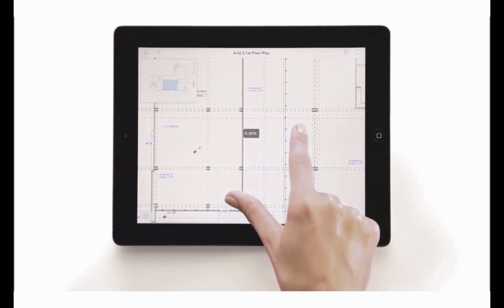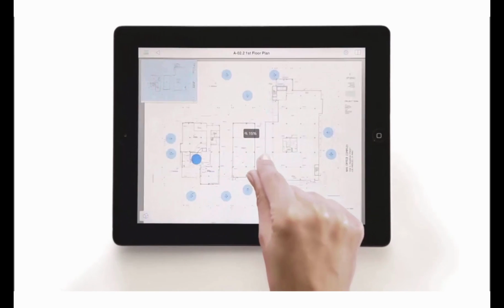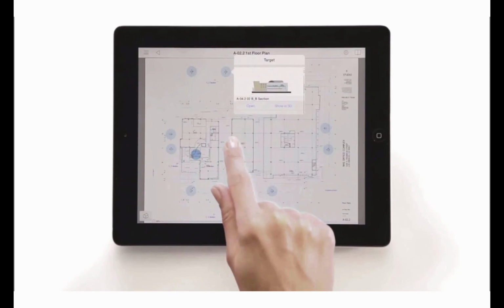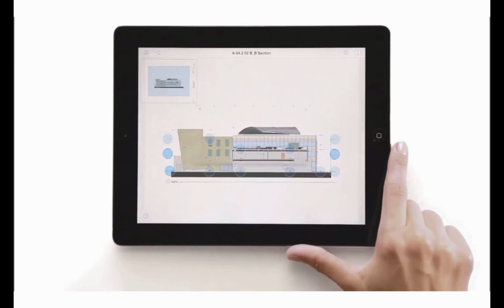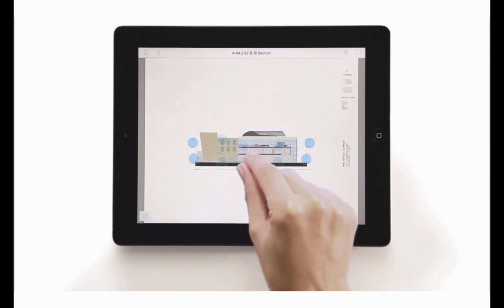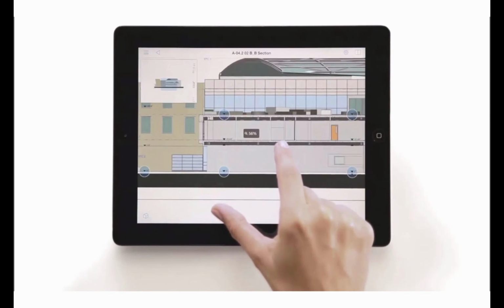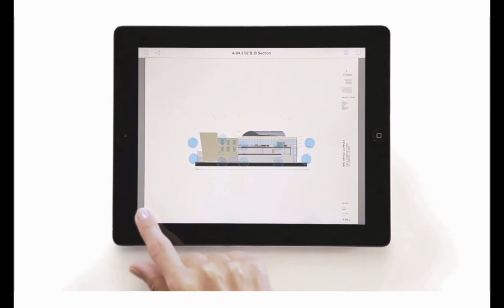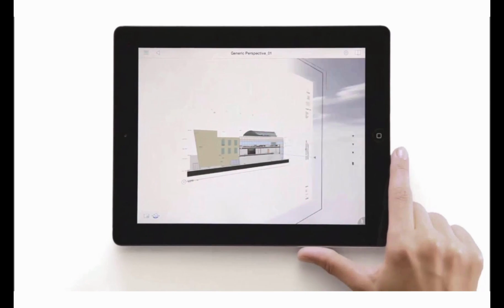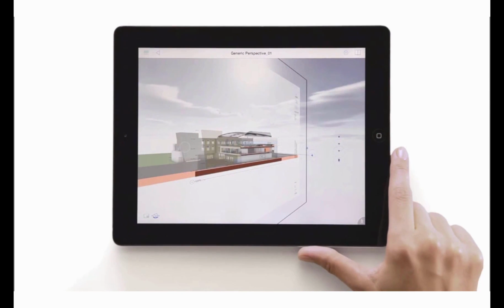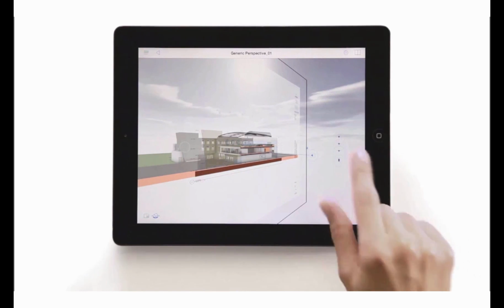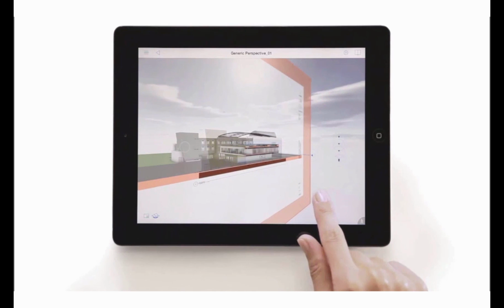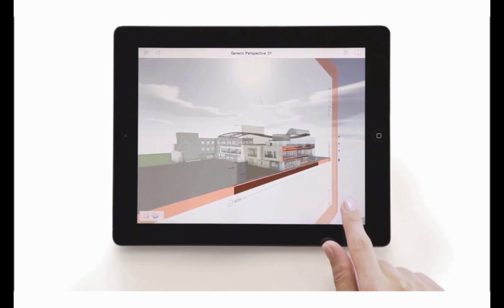Let's use this marker to display a section view of the project. The section view also contains additional markers of the corresponding detail views. And then you can also return back to the 3D view from this section. Note the smooth transition, providing you a better understanding of the relationship between 2D and 3D. Keep in mind that the 3D cutting plane can be repositioned with the help of handles to give you an easy tool to check the details of your BIM right in 3D.